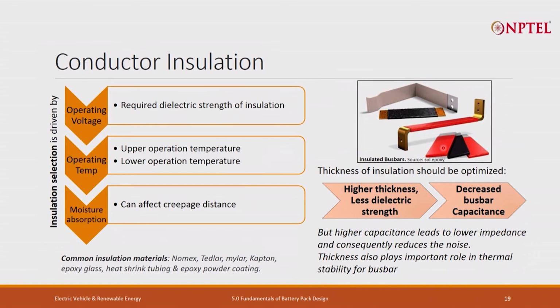If you keep on increasing the thickness of the insulation material, it starts decreasing the dielectric strength, because air is considered to have a very high dielectric strength. Any material is generally inferior to air. So, as you keep on increasing the insulation thickness, your dielectric strength comes down. So, there is always a trade-off up to what thickness you should go.